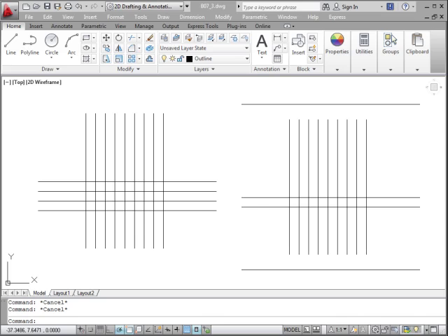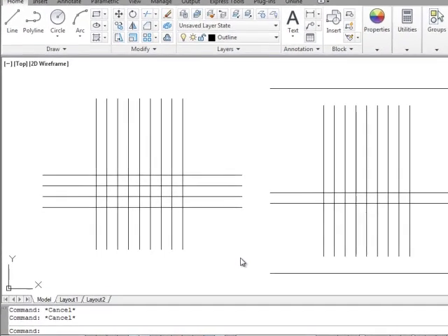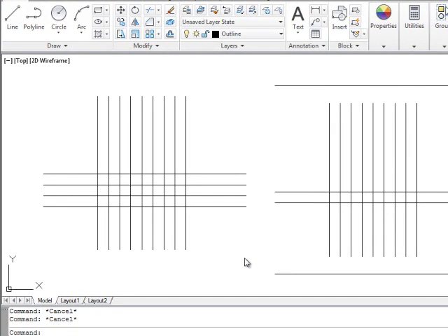In this video, we're going to talk about trim and extend. The trim command allows us to shorten objects or remove a part of an object, but you can't remove the entire object. For that, obviously, we just use erase. In order to trim, let's say we wanted to trim this one line at this point, where this horizontal line comes across. We want to trim this part of it up here.